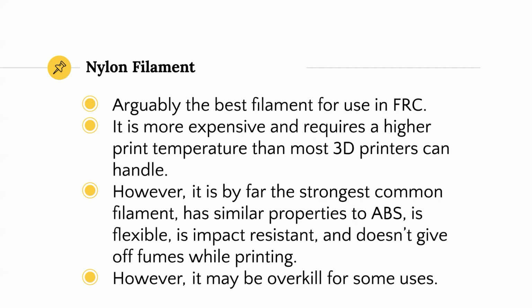Nylon filament, my personal favorite, however, the one I use the least. This is arguably the best filament for use in FRC. It is more expensive and requires a higher print temperature than most 3D printers can handle. However, it is by far the strongest common filament. It has similar properties to ABS, is flexible, is impact resistant, and doesn't give off fumes while printing.